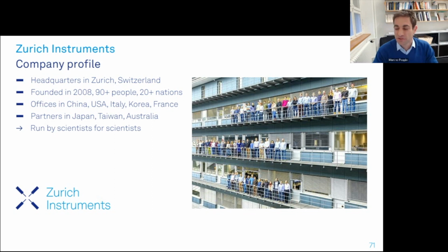Well, I could try to say something. I could infer what the question was. Perhaps the question was, can we make the nanowire tips sharper? Certainly that would help with the spatial resolution and is something we're working on. This heavily depends on the type of nanowire that you have and the way that you produce it. One of the more promising methods for producing sharp nanowire tips is the technique that I very briefly showed in the slides. We had some fully magnetic nanowires made of cobalt using a technique called focused ion beam induced deposition. Using these kinds of techniques, you could improve the sharpness much beyond what we've had until now, which is a tip size of order 100 nanometers, probably down to the 20 nanometer range.